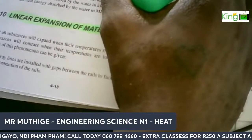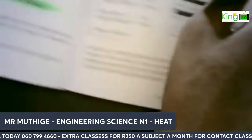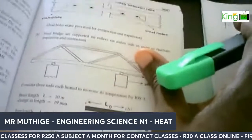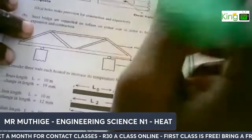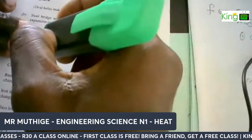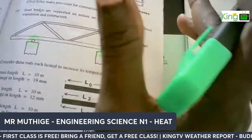And sometimes that can be very bad for business. Simply because if you find a bridge in expansion, there is a phenomenon that usually happens. That's why you'll see a bridge will always have roller wheels on the one side and rollers on the other. This is for it to allow for that expansion and contraction.